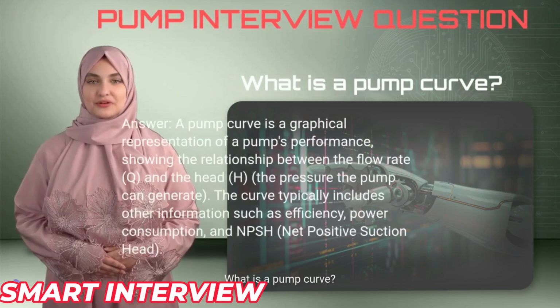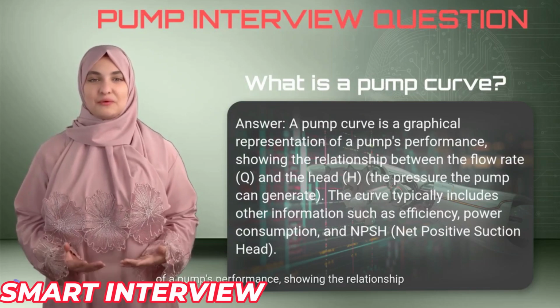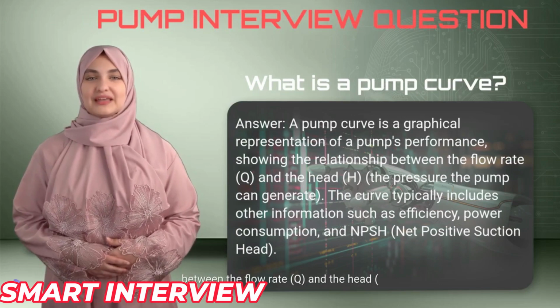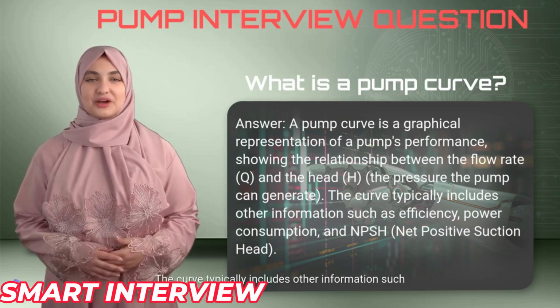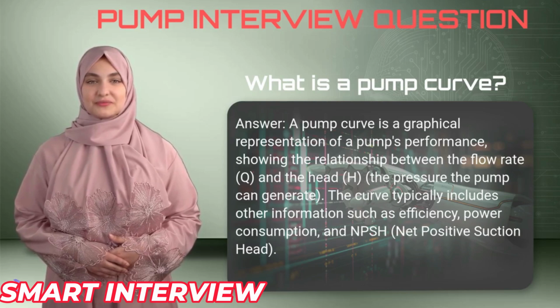What is a pump curve? A pump curve is a graphical representation of a pump's performance, showing the relationship between the flow rate, Q, and the head, H. The curve typically includes other information such as efficiency, power consumption, and NPSH.